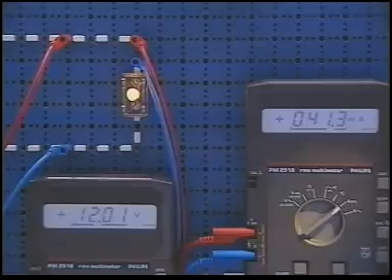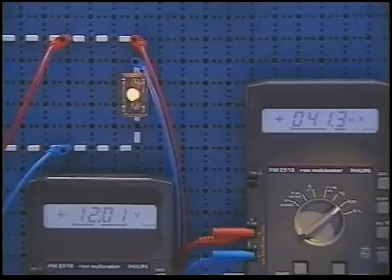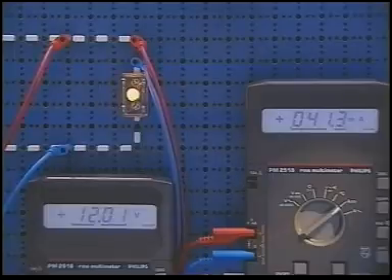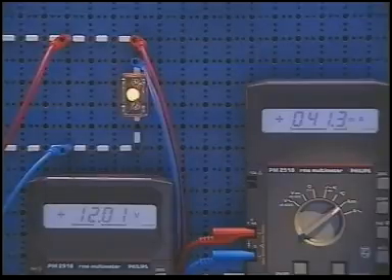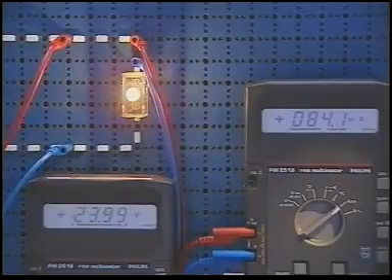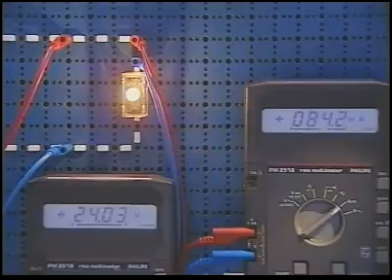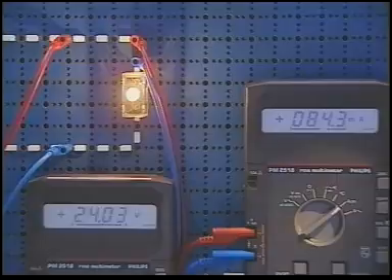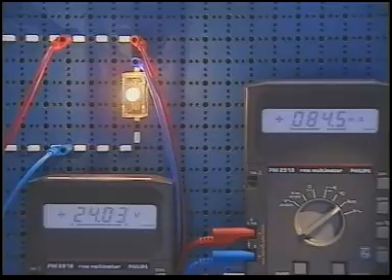But why does the lamp illuminate, and why at different levels of brightness? Here too, Ohm's law provides the answer. The filament of the lamp has a resistance which we will assume to be constant. When a voltage of 12 volts is applied, a current of 41 milliamperes flows. Because of the frictional resistance, the filament is heated by the flow of electrons to such a degree that it begins to glow. If we increase the voltage to 24 volts, the current also doubles to 84 milliamperes. In other words, twice as many electrons are forced through the filament and it gets even hotter. The lamp glows brighter.